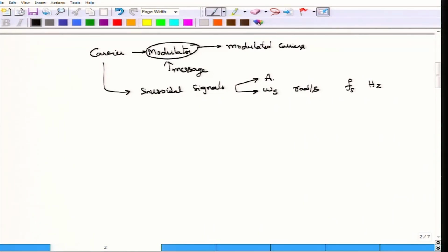So, it has amplitude A. Equivalently, you can characterize this by a power P. Normally, you do not do this, but in optical communications, power is the only thing that you can actually measure. You cannot measure the amplitude of a light wave. Therefore, power becomes the fundamental component in an optical communication system. So, we represent that, and again to distinguish that this is the power of the signal laser, we put a subscript Ps.